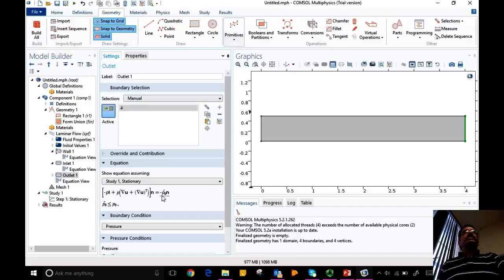Now, the outlet boundary condition is always a challenge, even in real experiments. Imagine that you have a tube and you're pumping fluid from this side at a constant velocity. How does the flow profile look on the outside? It depends on how much flow there is. You can imagine a garden hose. If you have a full-fledged flow, it's just going to go straight with very high velocity. Start turning it down and down and down, and air may actually go into it.